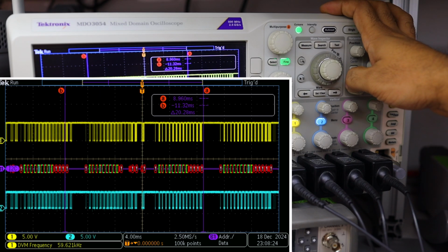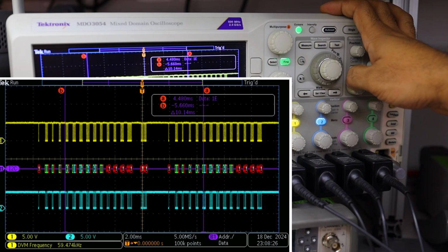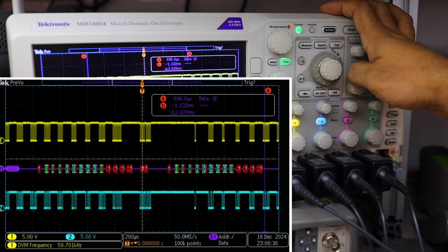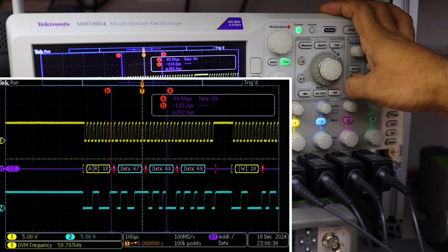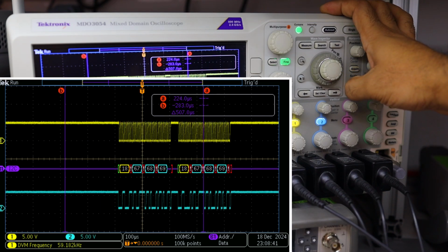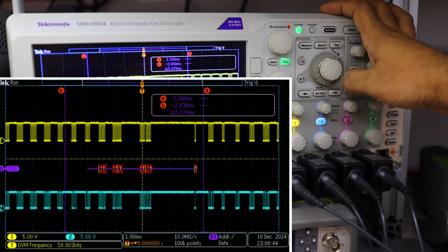There are still some quirks, and the other packet, which is supposed to be at 54787B, is not being displayed here because it's different data, I believe. So with the MDO3000 also we were able to find the appropriate trigger condition with the bus, and I believe that's it for this oscilloscope.